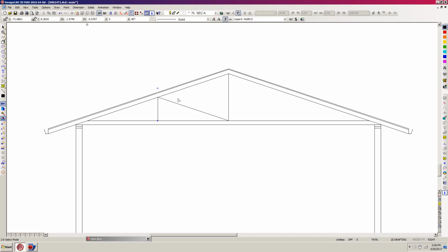So now these are the basics of my truss webbing. Now these are all, when I click on them, you can see that they're individual lines. So I'm going to cheat a little bit, and I'm going to hold down Shift and click near the other two lines and hit B. So B combines the lines. Think of B for combine, I guess. You click near it and you can see that they're all combined into a single line now. Hit Escape.